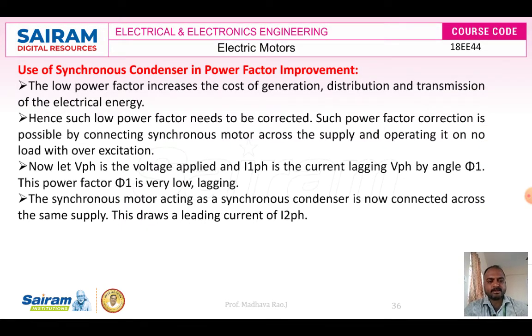The power system consists of various components: generators, transformers, and transmission lines. Due to the inductive nature of the loads, the power factor will decrease. To improve the power factor, we use the synchronous condenser. Induction motors and inductive loads decrease the power factor, due to the lagging power factor angle. So, for low power factor,